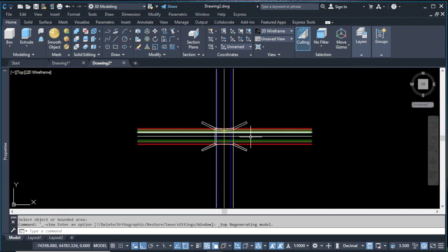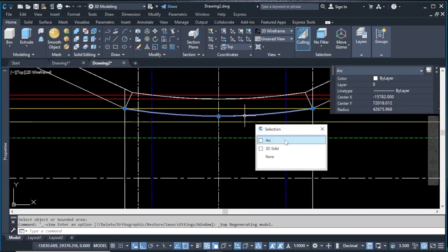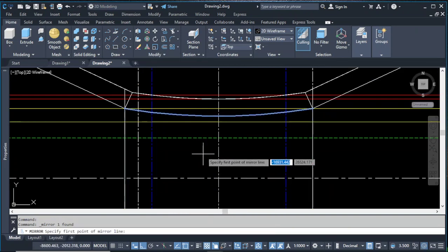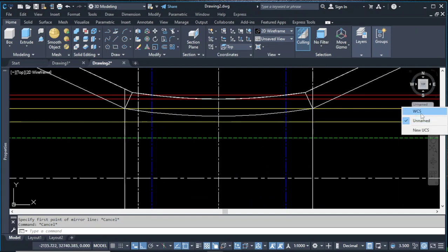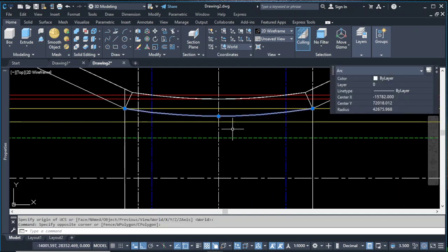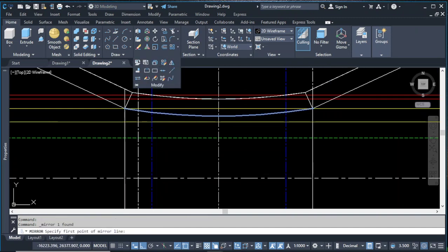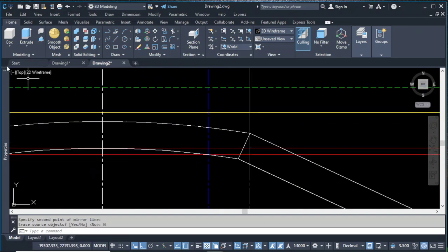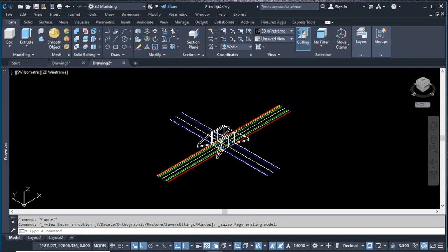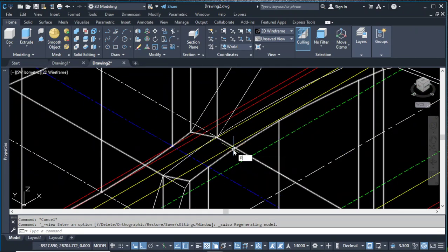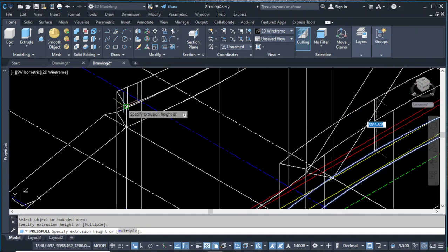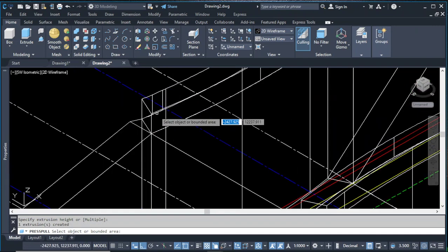So we just come top again, we pick the arc, then we mirror the same, and now we need to get back to the UCS, the world UCS. So we just come back here. No, let's do the same on the other side. So we try to press pull again. Yes, we can do that. So I can also align with this point like that.